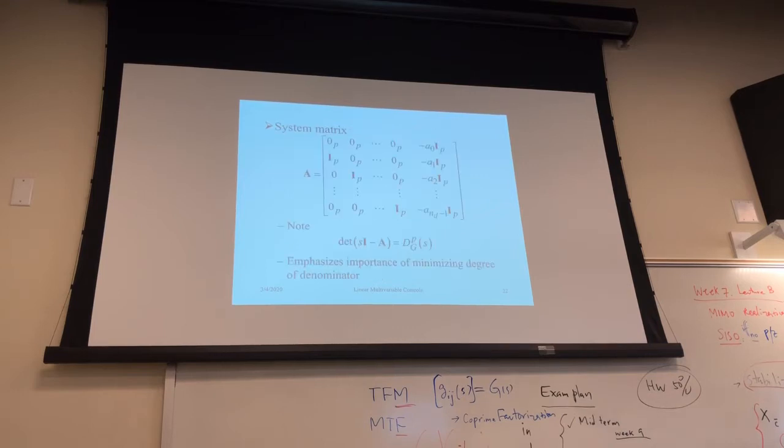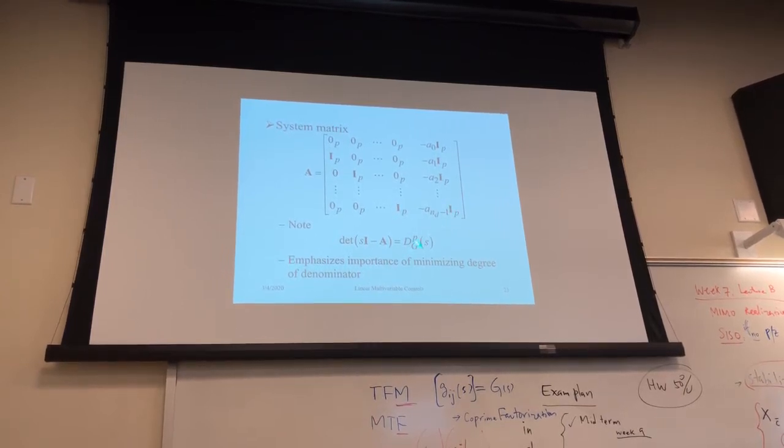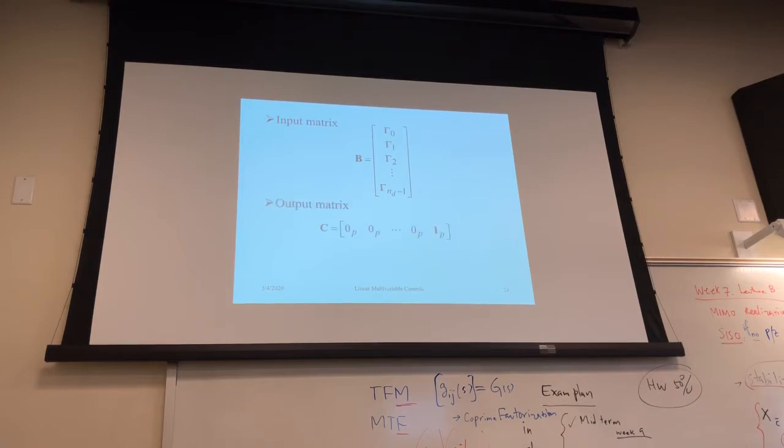So then you can write something very similar to the canonic form. Observable SISO case, observable canonic realization form with the block diagonal of I_p. Okay, so then in the end, your characteristic polynomial is d to the power p. So again, B is like C transpose, C is like B transpose. The feed-through term D is 0 because it's strictly proper. So you realize that way is always observable for sure, but it may not be controllable. You're not that lucky.